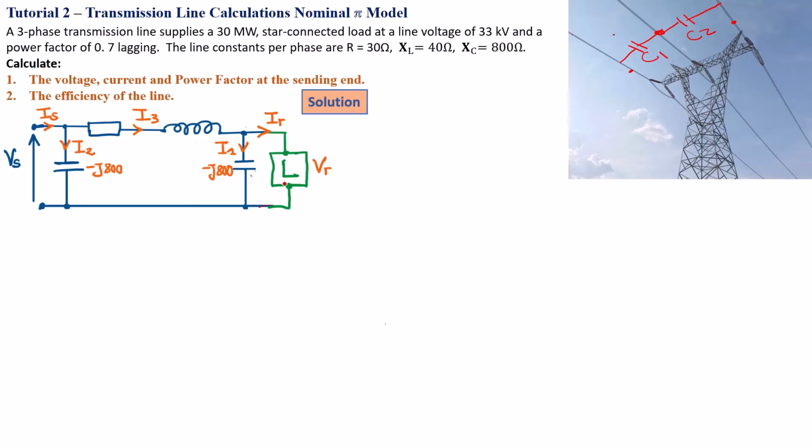Now, let's assume that you are sitting in an exam class and you've been given this power system problem. So the first thing, obviously, you need to read the problem statement, understand it very well, know the given data and what's missing so that you can answer the question. So here, our given data, very simple. The first one is active power. Now, this power is at the receiving end, okay? Then it is at a power factor of 0.7 lagging. That means the angle is negative 45.7 degree.